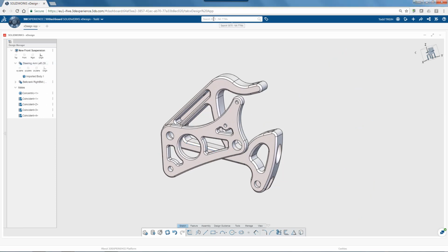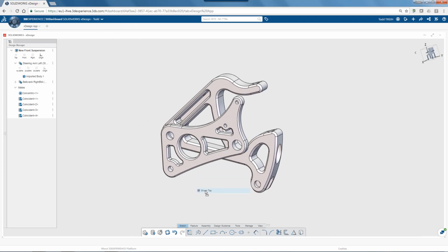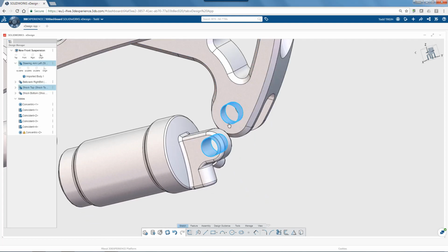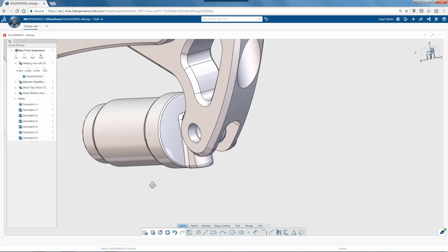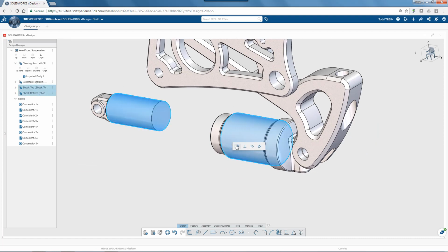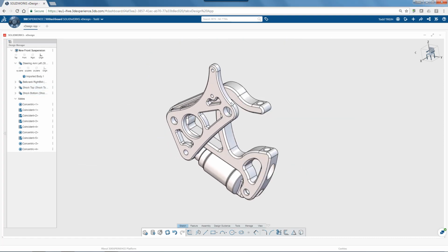The suspension needs a shock, so I'll add the top and bottom components. Same procedure as before. Search, then drag and drop. With both components in the workspace, I can move them into a more convenient position for mating. Concentric and coincident mates are all that are needed to assemble these parts to the bell crank and the steering arm. The assembly moves properly, but there's nothing controlling the stroke.